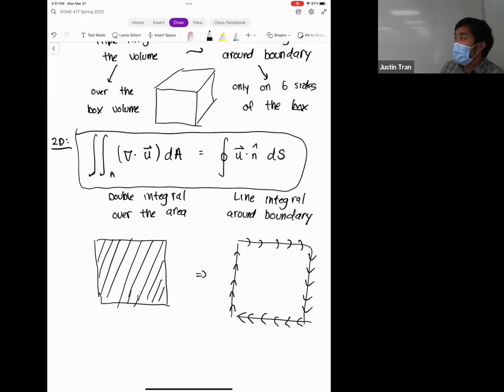This is a key concept in fluids because with the transport theorem, if you integrate over the entire volume, then we can transform that into just whatever fluids enter and leave. Yeah, so it's the exact same idea. And that's why finite volumes has strong roots in fluid mechanics.